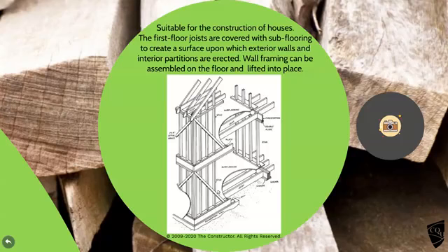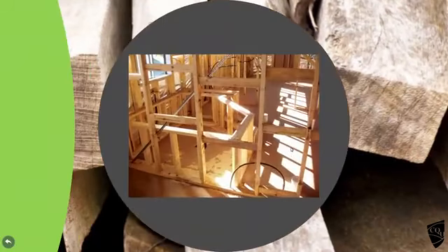So this is timber flooring down here. You lay your foundation, put your joists down, bang, floor surface, and then on top of the floor surface you build your partitions and your walls. Okay? You can build most of the framing on the floor and then lift it up into place. That's quite a common way of constructing it. There's a picture, just a bit of it. You see, those internal partitions and that external wall over here are built straight off the first floor.